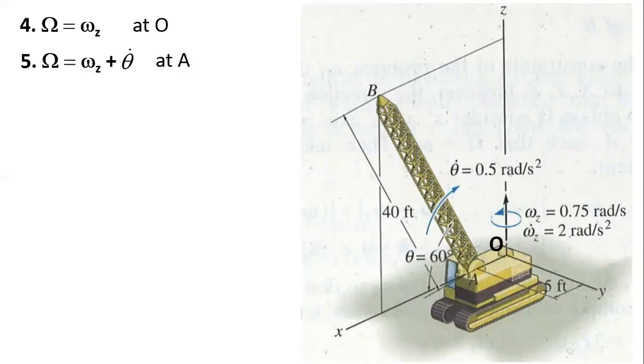So that's just going with this one. Okay. Then what's going to happen is we're going to have some different things in our rel term, right? But it's actually okay. We can set up, let's just say we were doing our velocity, right? And let's do our velocity. So let's say velocity of B is going to equal, okay, and we said here we wanted to start it with O. So let's do velocity of O plus our capital omega crossed into R of B with respect to O, plus we've got some sort of VB rel term, okay, or we also call that R dot.